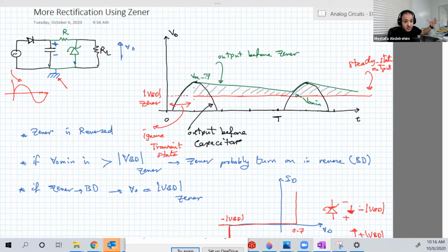because if it's a speaker and you left the input, the output, like the one with the ripples, this green signal here, then you will hear some humming, some very small noise come out of your speaker. And if the ripple is big, this noise will be higher.